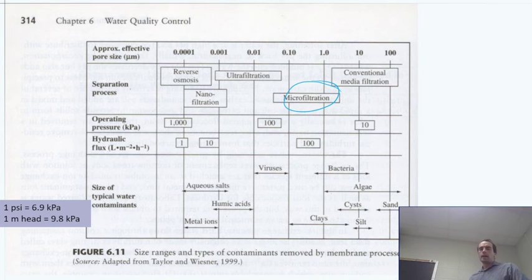If we go beyond that, we can get to ultrafiltration. So then we are looking at pore sizes around the tens of nanometers typically, so 0.001 micrometers, maybe a little smaller. We call this ultrafiltration, and if you notice, we do have some overlap. So the terms are a little bit of a spectrum in terms of what pore size we're in and what manufacturer decides to call it micro versus ultra. But generally, ultrafiltration can allow us to get down to virus removal.